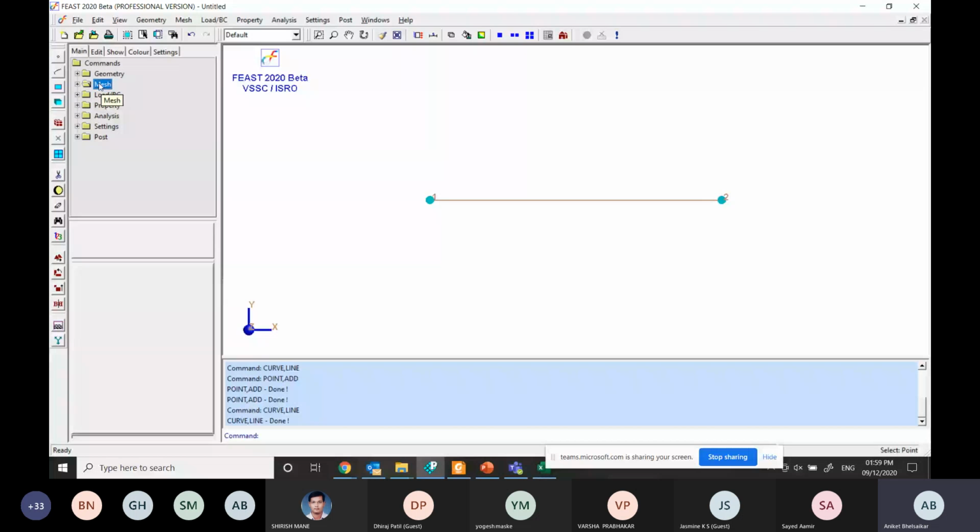In mesh, I'll go to FE mesh. In FE mesh, we have certain options. I'll explain these options. First option is called bar element or bar command. It's not element, actually a command. The name of the command is bar. But this option can be used for meshing 1D. So 1D geometries, if it is there in your complete model, you can use this bar command for 1D mesh.